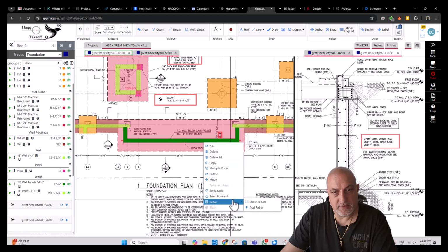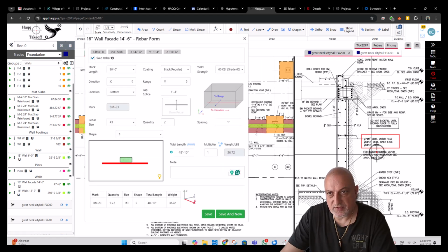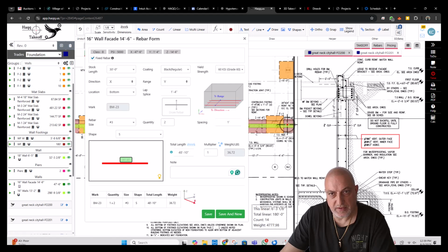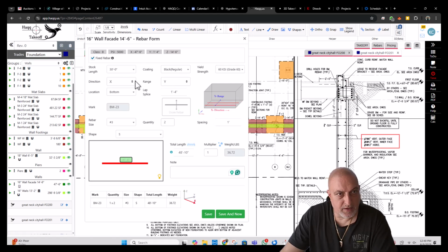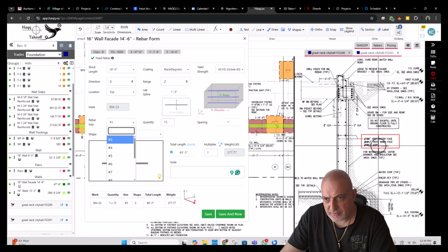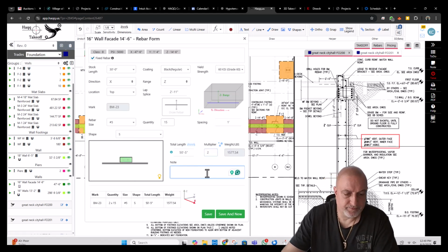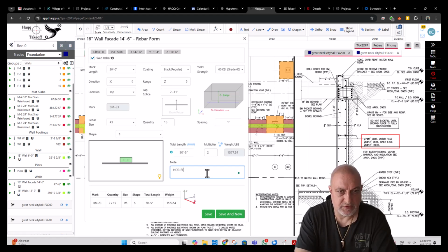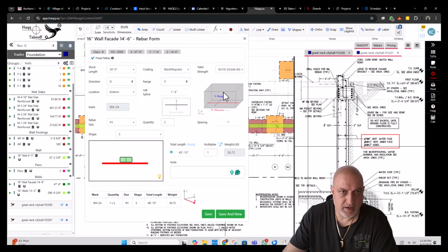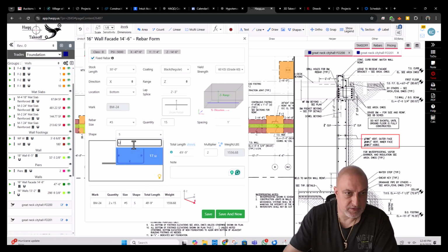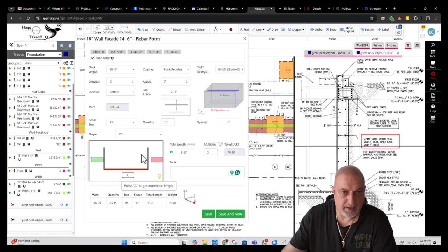Okay, now let's add the reinforcing. We're gonna adjust this reinforcing. That will cover at the top as well. Grade beam will come later. Okay, horizontal bars. Horizontal bars is number 5, 12 inch on center. Times 2. Horizontal each face. I'm gonna do horizontal bars again for the corner bars, and we forgot the corner bars on the other one. And times 2 is the regular each face, this U shape, L and L.